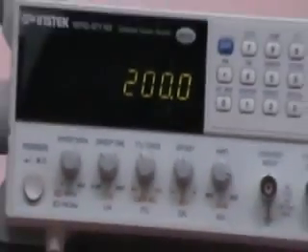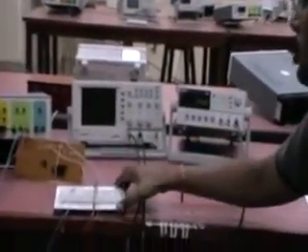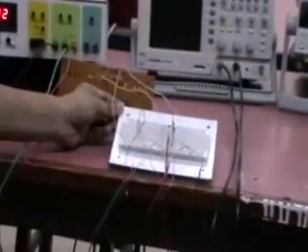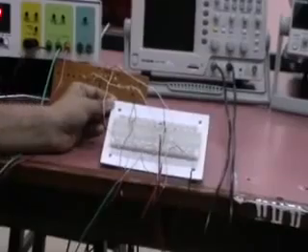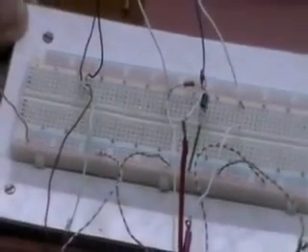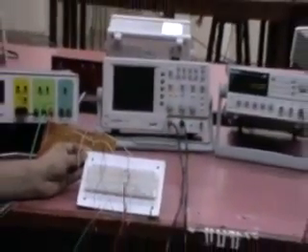By switching on the DSO, the interconnections are done according to the diagram that is given. As you can see, the Q input is given across the resistor, and the P input is given across the diode. So the differential output will be the difference of both Q and P. By keeping XY mode, we can observe the IV characteristics. So now, to observe the IV characteristics, first we should switch on the DSO.